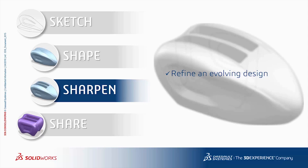Sketching right on the solid model, not to maybe turn it into a feature like Brad did with the button, but just to sketch on the solid model during a project review meeting and say, hey, maybe we take some material off over here, or if we added the control panel in this area. Really amazing benefits to being able to sketch right on the solid model, as well as taking parametric features that we all know within a 3D CAD system, like cuts and chamfers and fillets and draft and shell, and applying that to our sub-D solid body that he created in the initial step.